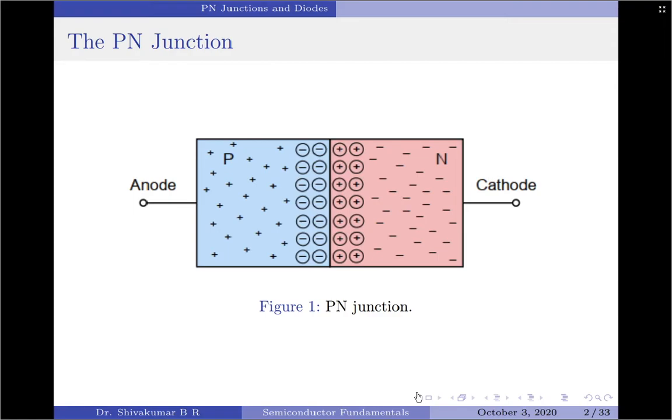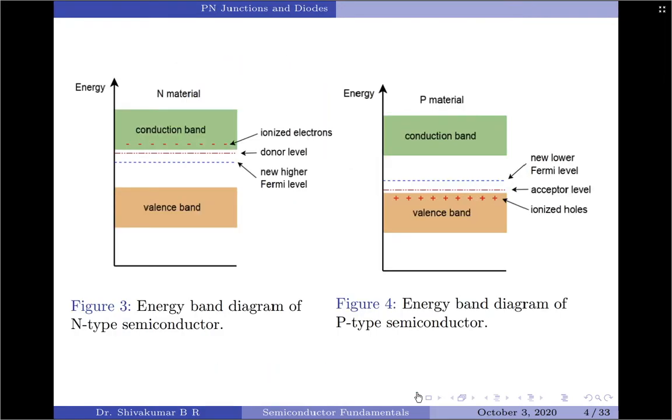To understand the concept of energy hill, recall that in the previous session, it was discovered that doping an intrinsic crystal would shift the Fermi level. For n material, the Fermi level is shifted up toward the conduction band. In contrast, for p material, the Fermi level is shifted down nearer to the valence band. This is indicated in diagrams here.